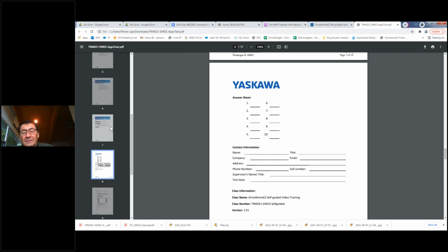I've done a bunch of similar kind of things where you have a little bit of logic where you need to switch things based on a sensor input or a combination of sensor inputs, like the trash can has to be in position or an object has to be in a place before you're able to run. And then your run is conditional, so you want your run to go until it hits a limit or a sensor turns on, things like that, and then you turn the run command off.